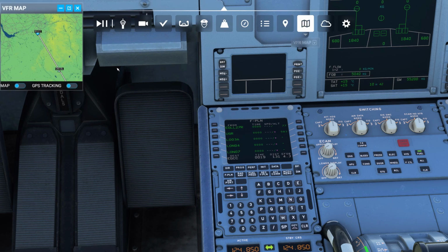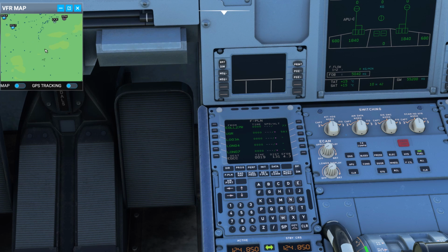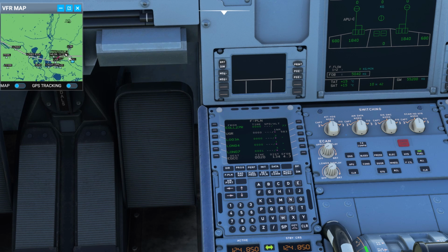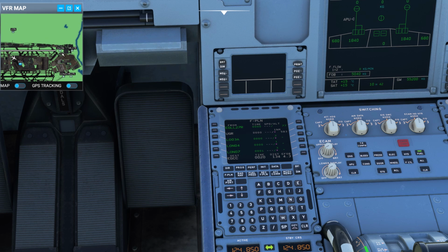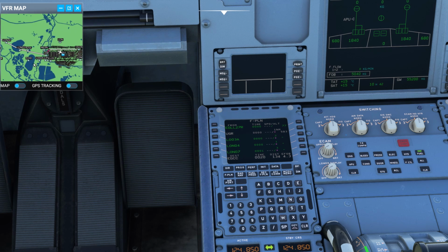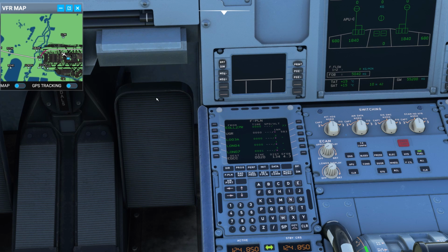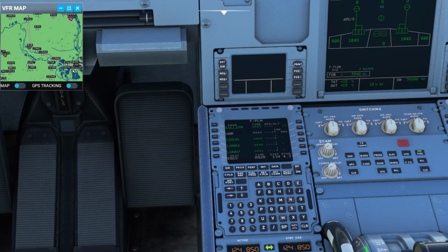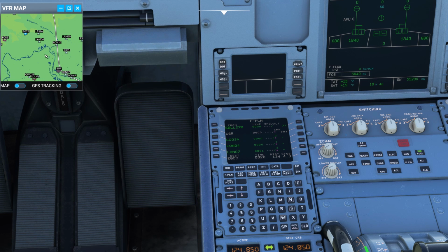Okay, let's have a look what that's done to the actual map. So you can see now, rather than going point to point, it's now routing from 27 right, out on the departure route. What you may want to do is get rid of this USR waypoint, because you see how it takes off and drops me there. I'll show you in a second. So that's going to take me out and round, and it's following this departure route, which actually hits a waypoint I already want to hit.